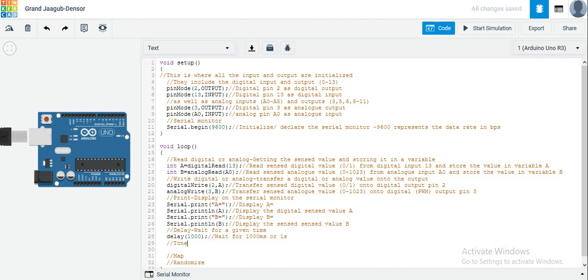Then under tone, this one you're going to use a buzzer, and in the buzzer you're going to apply a frequency. So apply a frequency of a given value onto a buzzer, of course, connected to a given port. The port will be an output port.